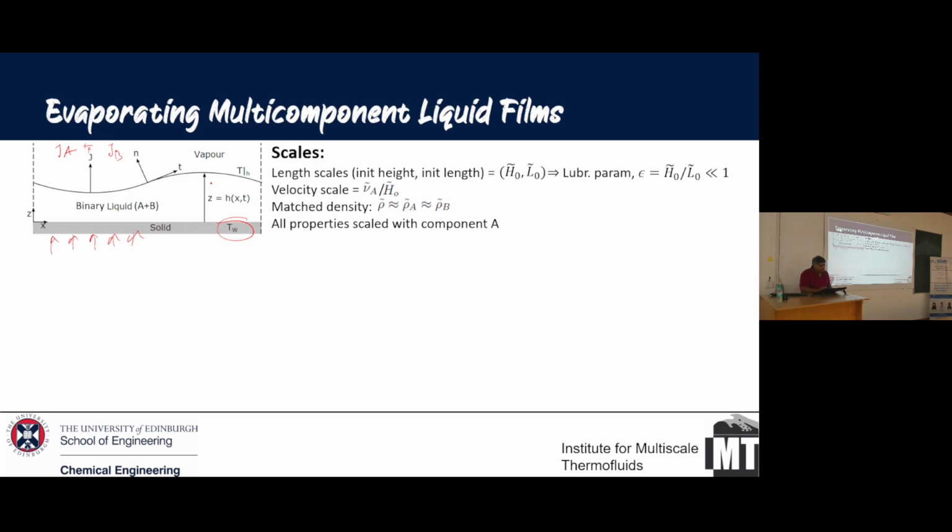And one of the things you can imagine is these are very thin liquid films. And the example I'm looking at is a water ethanol film, which is about 1 micron thick, or around a micron thick. Okay, so these are very thin liquid films, and you are evaporating these things to develop a pattern. Okay, so here one of the quick things we can look at is if we say that the initial film thickness is around h0, okay, and the length of the film is L0, and here this is a very thin film over a very large surface. It could be on a chip or it could be on your silicon wafer.